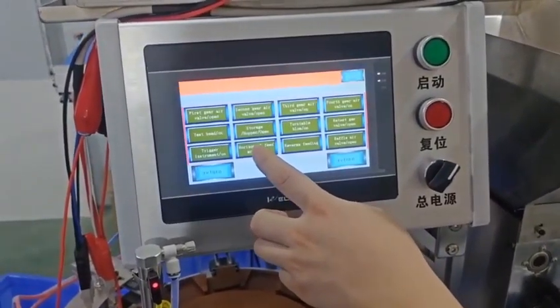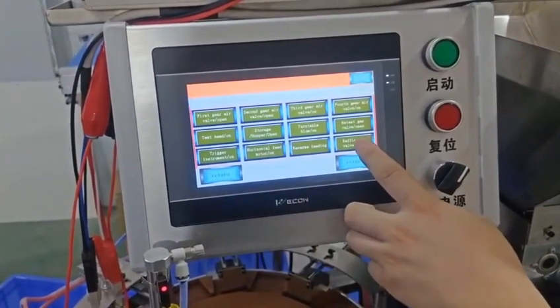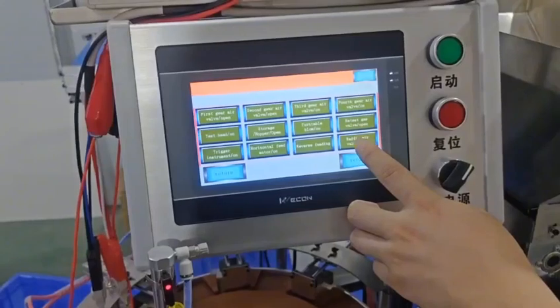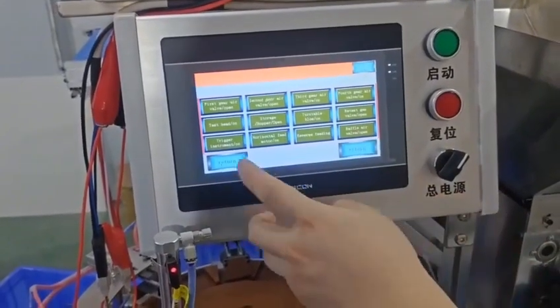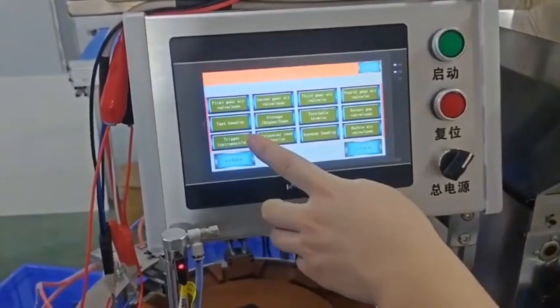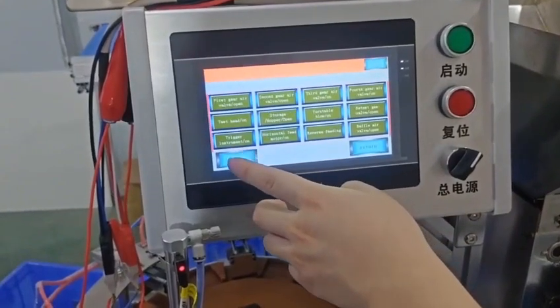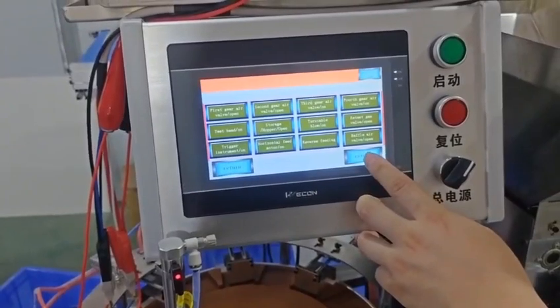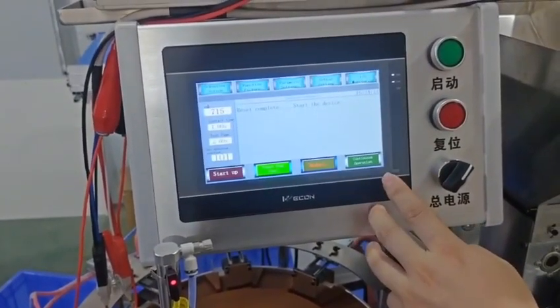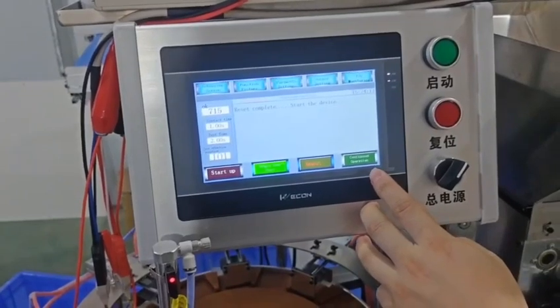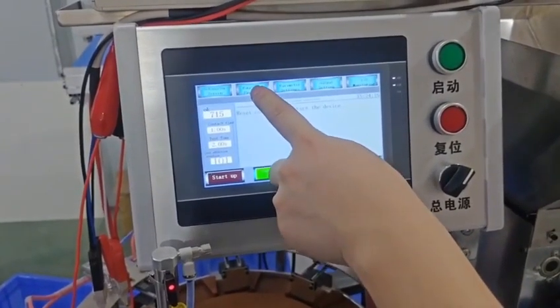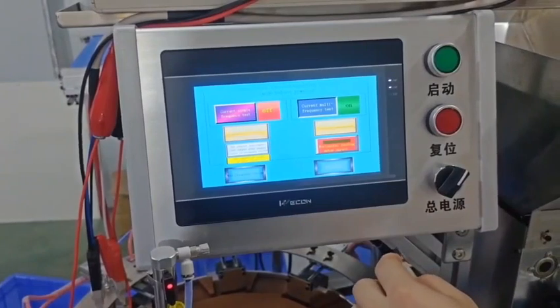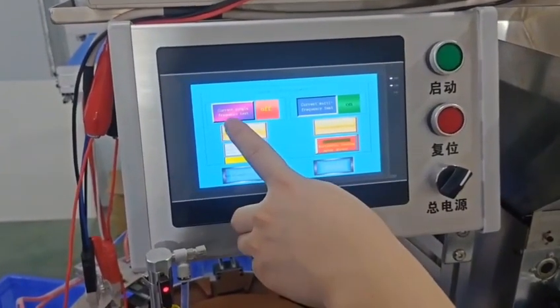Initially, the parameters include contact time and test time, which can be set here. Additionally, settings include feed detection delay, horizontal full feed delay, and the desired precision. On the right, you can set the turntable speed and push time. This includes the feed time, main motor stop time, and main motor run time. Also, the reset count, which specifies the number of resets per time.